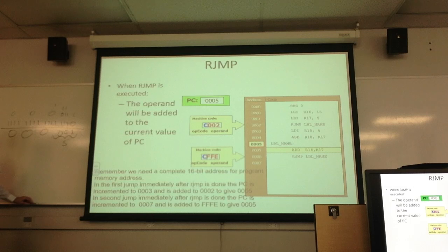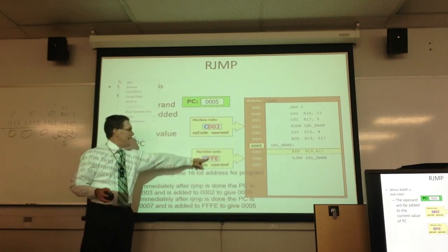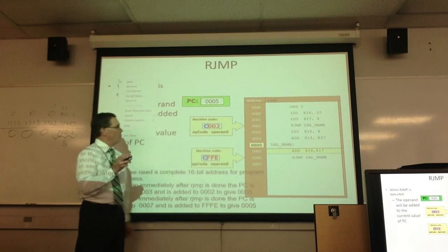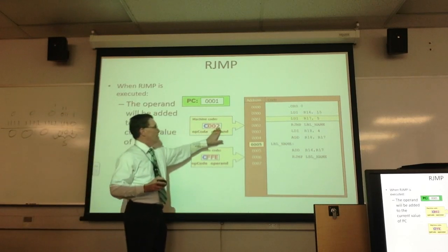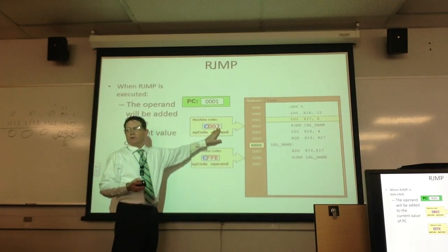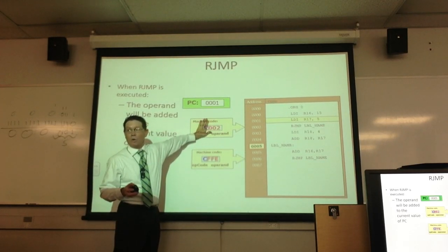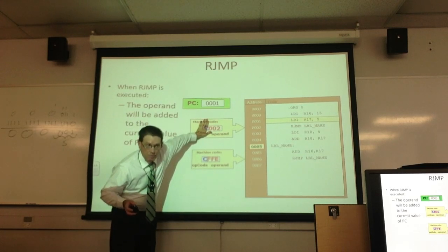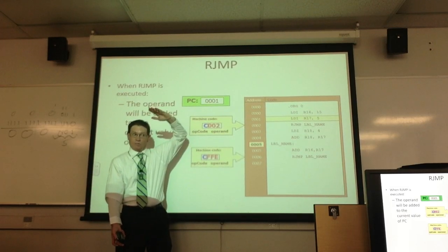All right. That's brought in. It just takes care of the 2's complement. Whatever that number is there, it's copied. If we go back, watch what happens when we come forward. Again, how many bits is this, Michael? 12. And how many do I need to address flash? 16. Unless I've got big flash, which needs 22. But right now we're going to be working with 16.